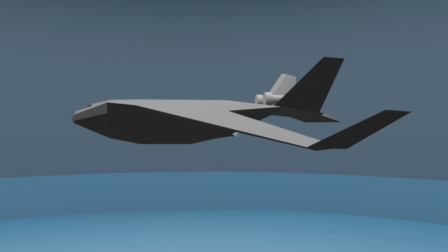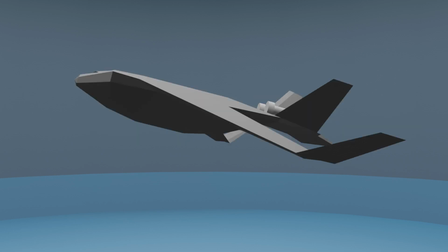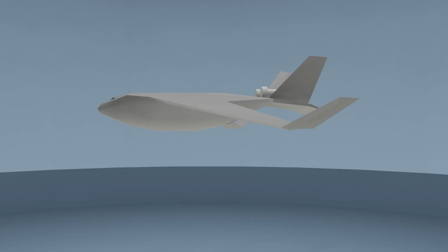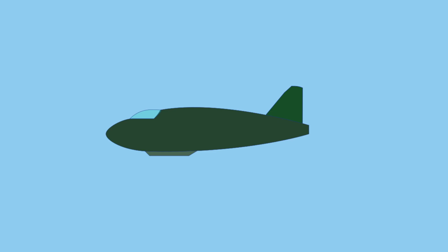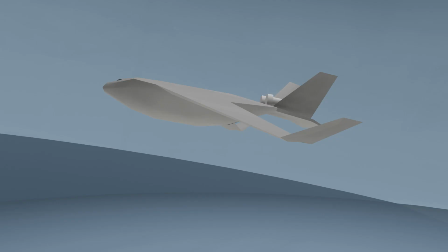The one question that does have to be carefully considered is stability in the y-axis. That's the pitch axis. That's the front of the plane going up relative to the back of the aircraft. Eric Brown, the British test pilot who is credited with having made the most aircraft carrier landings in one lifetime and having flown the most different types of airplanes of one person in one lifetime, said that the only tailless aircraft, an aircraft without a horizontal stabilizer, that flew well was the Me-163, which was the German rocket fighter of World War II. He said he flew about 5 other tailless planes, and he thought that every one of them was trying to kill him.